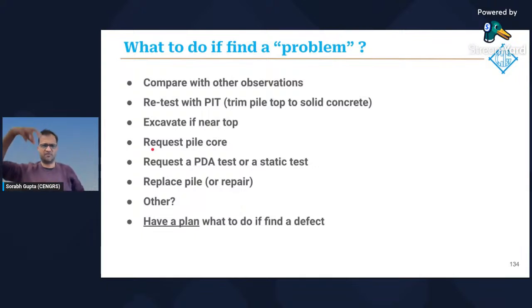at deeper depths. We can also core through the pile using a hydraulic core drilling rig. You can get cores of the pile concrete with depth, and sometimes that's good in case you have things like soil inclusion or honeycombing or weak concrete, or you have cracks in the concrete. Then a pile core can actually give you some fairly good validation of your PIT data.